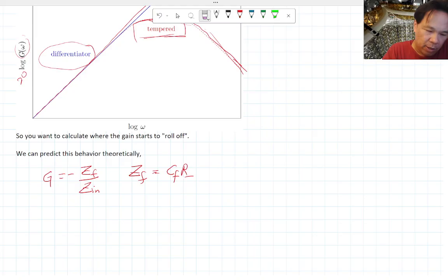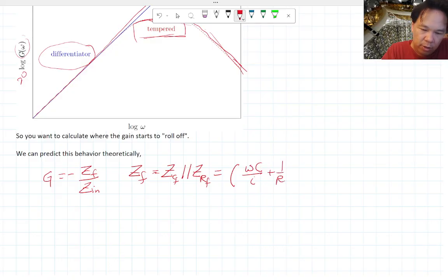Okay, oops, it's not multiplied together, they are parallel to each other. So it's the impedance of this resistor F. Well, things that are parallel to each other, we do this 1 over thing. So this is going to be 1 over i omega C, which basically puts the omega on top and the i in the denominator. And the resistor is just a resistor. So that's pretty simple. All this to the -1 power. The common denominator between these guys, I'm going to put an R_F on top and an i on top there. And then once I have the common denominator, I can flip it upside down. I'm just multiplying by 1 on both terms. Okay, so it's i R_F on top, and then 1 plus i omega R_F C_F on the denominator.